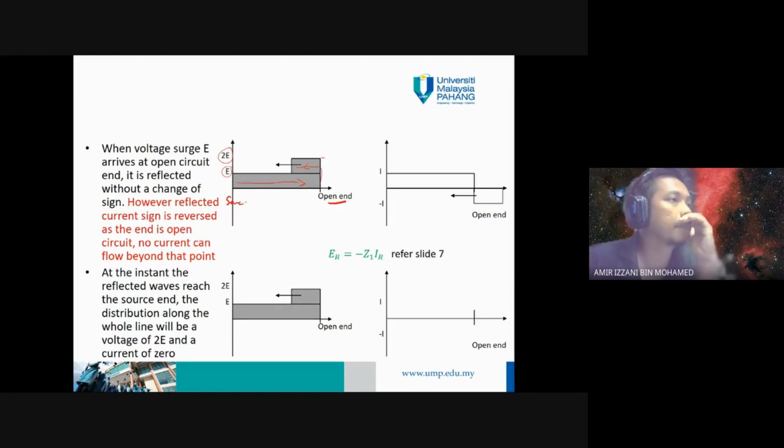However, the reflected current sign is reversed, as the open end is an open circuit, so no current can flow beyond that point. So no current will return back.